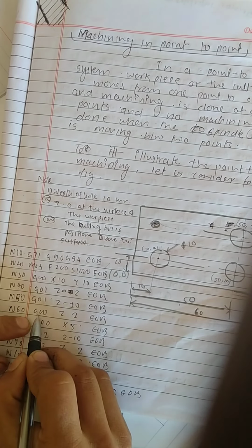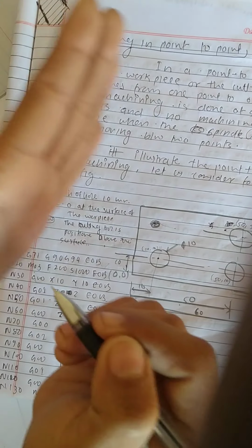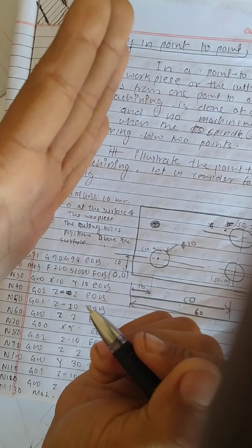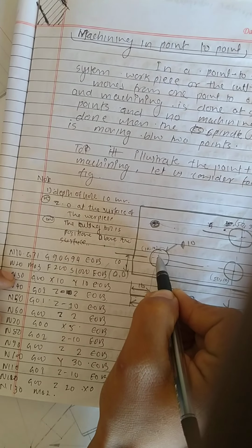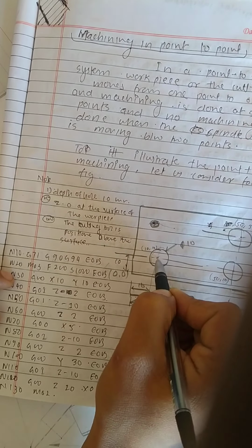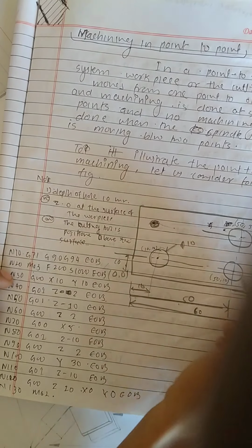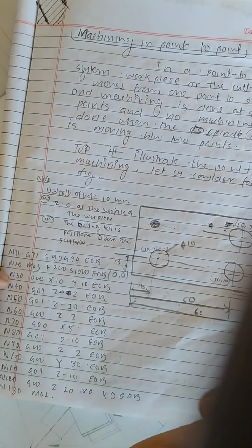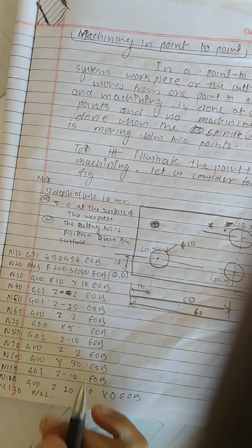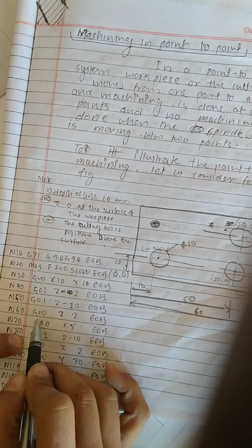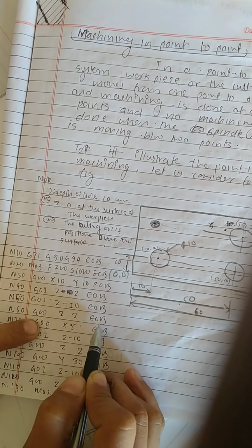And then rapid transfer, G00 Z2, means come above, 2 mm above the work surface. It makes the hole at this position, then comes 2 mm above and goes to the next position, does the same work, and then comes back up. Now you may have understood what I want to tell you guys. G00 Z2, end of block.